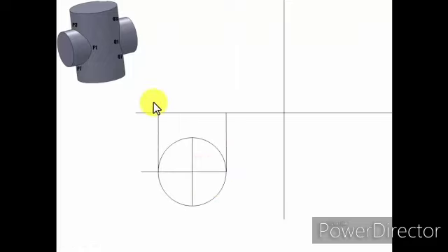Now guys, just think about this. This is the vertical cylinder. From where can you see the true shape of its base? One thing is for sure, the base's true shape can only be seen from the top, and hence we're going to begin by making the top view first. This circle has a diameter of 80 millimeters. We'll now proceed by making the front view, and it's going to look something like this.